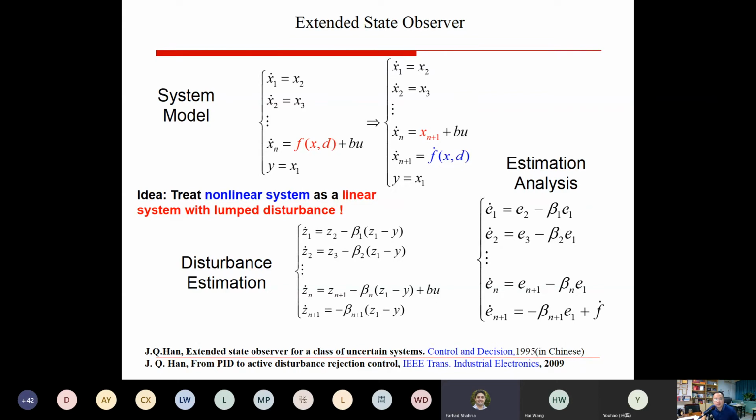You mean for the experimental result, how to create a periodic disturbance? That's right. But usually they exist in the system. For example, in the DC-AC converter, the output is the AC voltage, right? It's periodical. Then if you make some load variation, you will cause a variation of the voltage. Because it's AC voltage, the disturbance should be periodic.